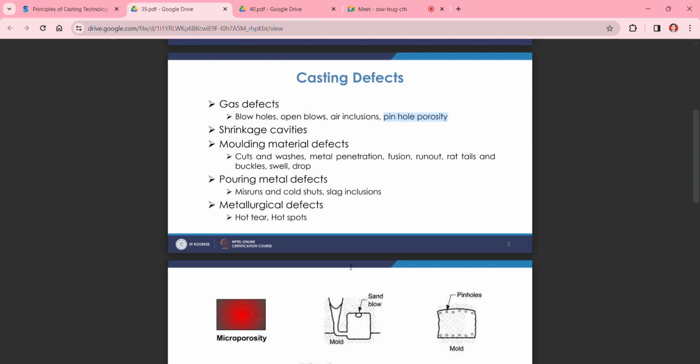Due to this solidification shrinkage, it can distort the final size of your castings. So to avoid that, you need to create your mold design in such a way that if shrinkage cavity defects are there, they should not hamper the final dimensions of the castings.